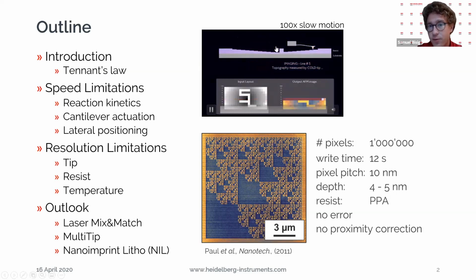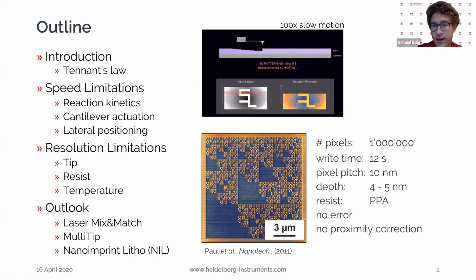And this we do in the forward direction with a hot tip. You can see how the tip is hot. And then we go into contact mode. We turn off the tip, so the tip is cold, and we just read back our image. With that, we get direct in situ information of the topography written. So that is how the NanoFrazor works.